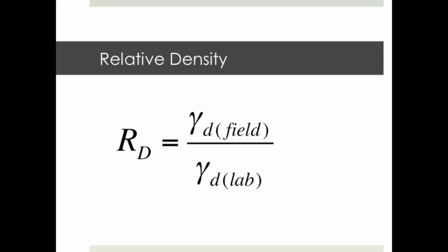To find our relative density or percent compaction, we always compare it to our maximum dry density achieved in the lab. If we were to go on a job site and measure the density in the field of a similar material, we could calculate its percent compaction. Also, if we had the in situ moisture content of the field material, we would know whether it is too dry, too wet, or just right.